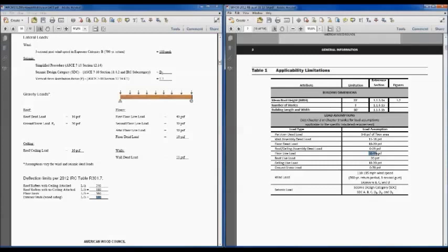we make the distinction between our residential and non-residential or light commercial structures. So for this document, we've got floor live loads of 30 to 40 pounds per square foot. And we know once you get into the commercial applications, those are going to go up to 60 or even 100 pounds per square foot. And so that's where you need to really pay attention and make the distinction if you're going to use this for commercial applications. That's why I mentioned a one-story building, slab on grade. Obviously, those floor loads wouldn't come into place.